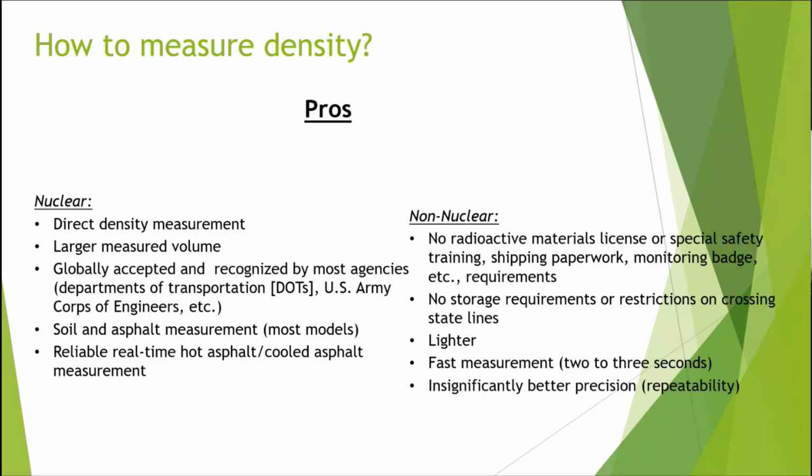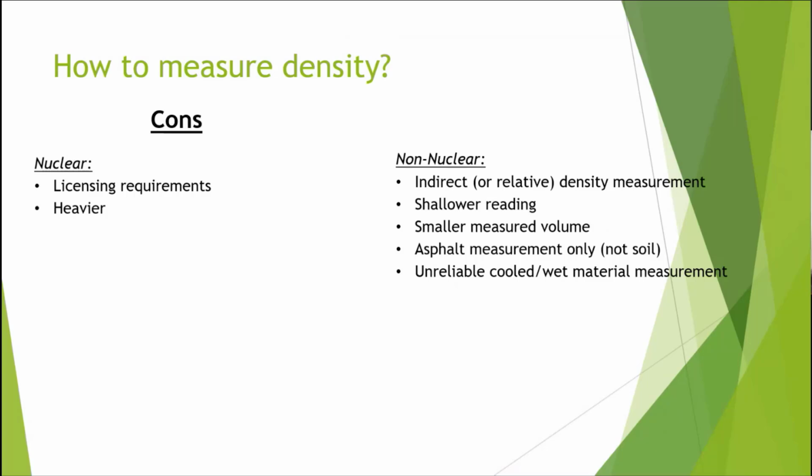Again, my takeaway on this is that pavement is not rocket science. It's like anything else. You get what you measure. And if you aren't measuring it, you're not going to get it. So the importance here is you have to use something that you have some confidence in to do quality control. Cores are really the acceptance. You can't go out there in the middle of a paving job unless you have a lot of dry ice and so forth and take cores and check it. That's going to be the next morning.